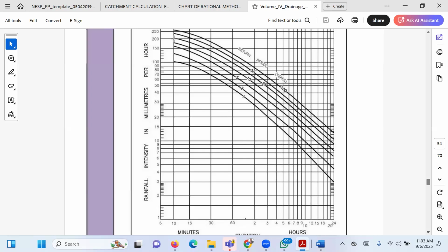If you design with 200, and the person designing for 1 year gets a drain size of 1.2 meters, I can bet you that your drain size will be 1.8 meters. That's true, whether you are designing for a retaining basin, a stormwater overflow, even a dam.